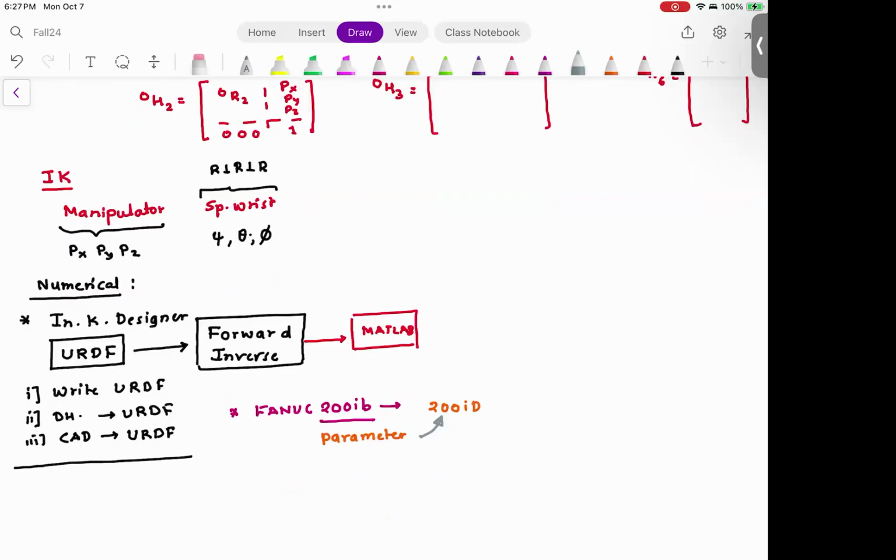Now understand, you are working with three different systems. You have your physical robot, you have the robot kinematic diagram that you have drawn and used to find forward and inverse kinematics, and you have the robot imported in MATLAB, which you are using to find forward and inverse kinematics with different parameters. Everyone understood this? The answers are not going to match unless your coordinate systems are aligned.